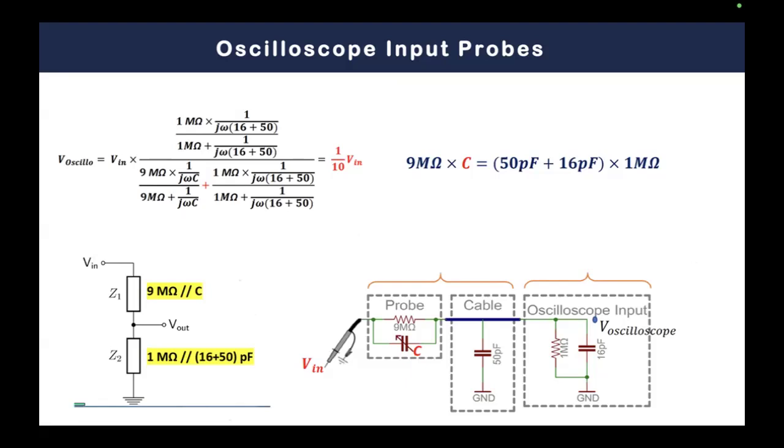If you have here C as a constant, when you go to the 1.2 mega ohm oscilloscope, there will be a mismatching condition, which will lead to an attenuation. But as far as you have this tuner capacitor, you will be able to move forward, up or down, the capacitance to keep this condition sustainable under different conditions. That's why we call this a calibration condition for the tuner capacitor.